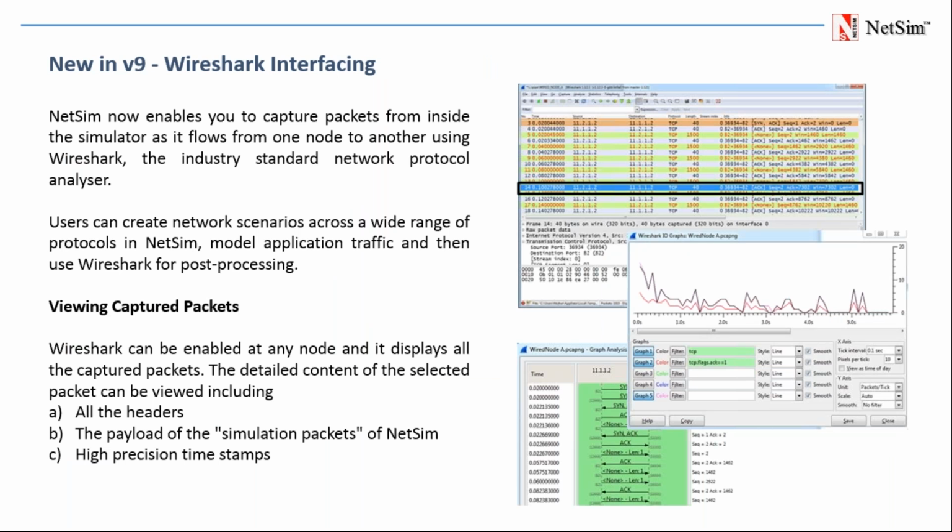It also has an interface with Wireshark. You can enable Wireshark in the design, and while running the simulation, Wireshark is active. As you know, Wireshark is a free and open source packet analyzer. It is used for network troubleshooting, analysis, software and communication protocol development. In NetSim, instead of performing some mathematical calculation and providing the result to the user, it actually generates the packets and transmits them within the simulated network. Hence, Wireshark can be used inside NetSim to capture these packets at multiple node locations and perform further analysis.